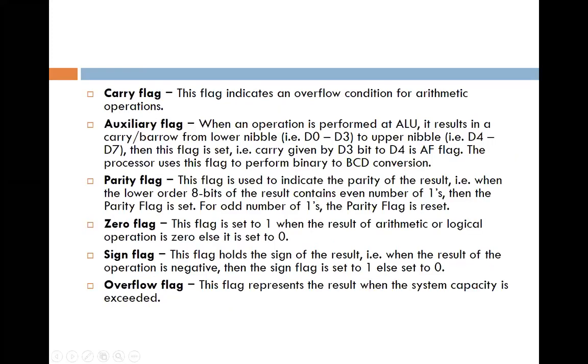Carry flag: this flag indicates an overflow condition for arithmetic operations. Auxiliary flag: when an operation performed in the ALU results in a carry or borrow from the lower nibble, that is D0 to D3, to the upper nibble, that is D4 to D7, then this flag is set.